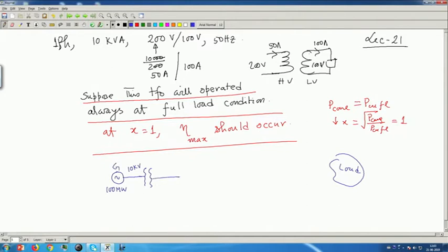I am drawing a single line diagram, and this voltage is stepped up to a very high voltage, maybe 200 kV, or even in our country we are having 400 kV level voltage. So, here is the transformer who does this. In transformer, kVA remains same. So, current on this side will now become less, and then you transmit it.